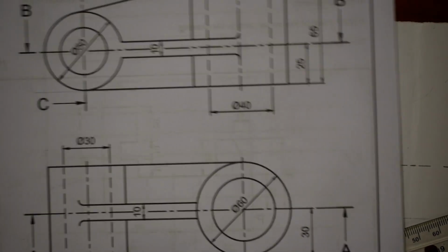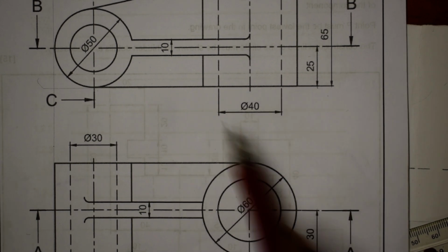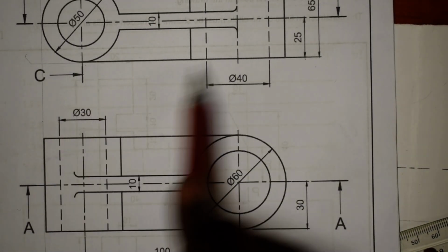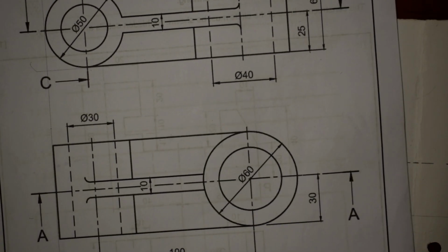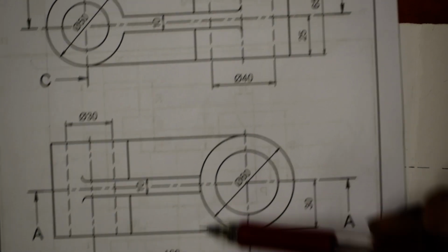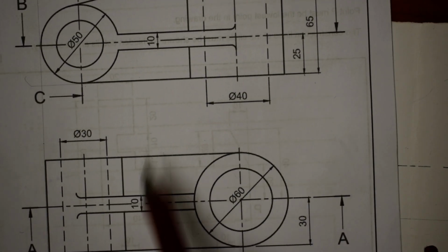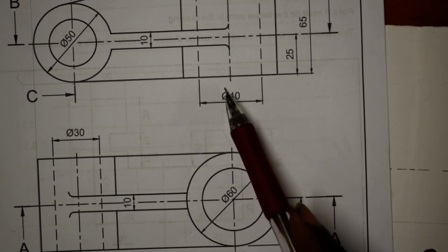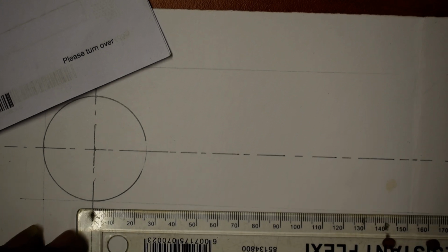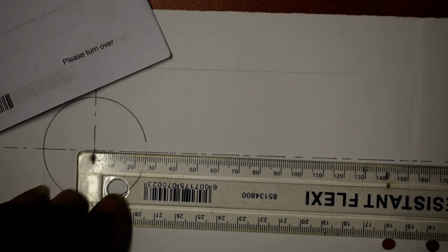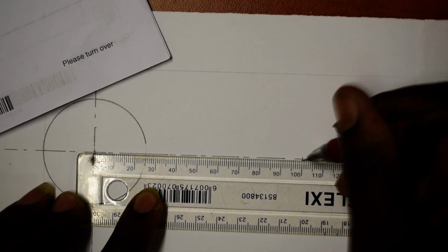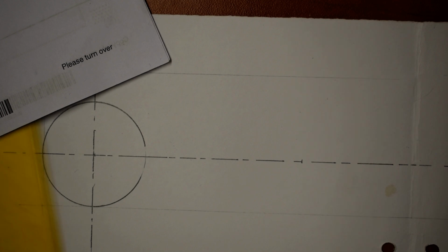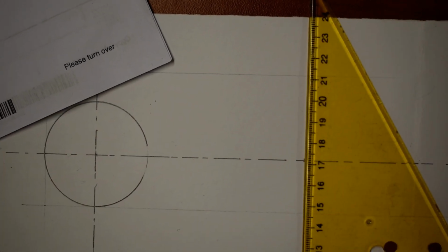Okay, so now what is happening now? So from here till somewhere here is how much? If you are not given the dimension there by your front view, you can still check it on the other view, because the front view as well as the top view will always share the same length. So from this center to this one, we are told what is 100 millimeter. You get it? So the 100 is up to whether you record it here or you record it here, as long as horizontal. So the 100 millimeter is ending here. Understand? So there's my 100 millimeter. So I can put another vertical center line.